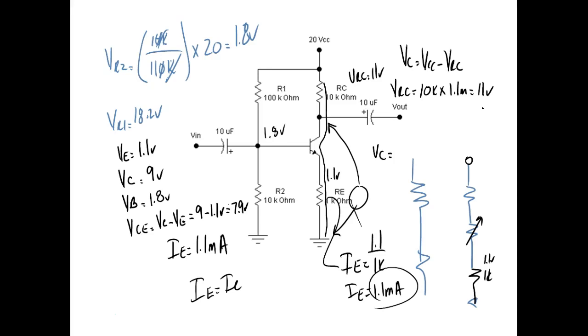So you just calculated the bias of an amplifier. And where did you learn every one of these formulas? DC. Every one of them. And these are not even complicated. Even though this is a series parallel circuit, we can treat these as two series circuits, right? What you've got to understand is we calculate this and ignore this, and we'll talk about why in a minute. So we ignore this resistor, but we use that voltage to give us this voltage right here.